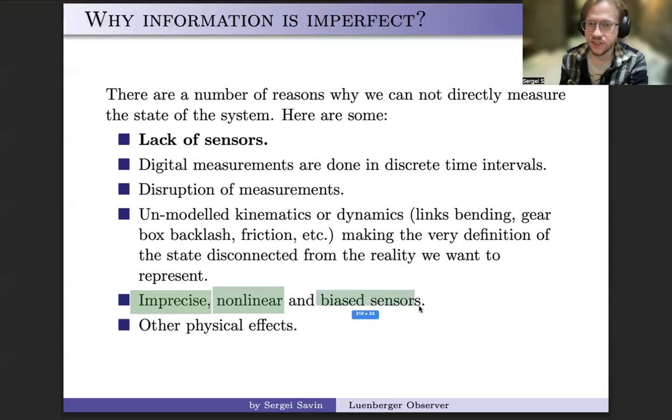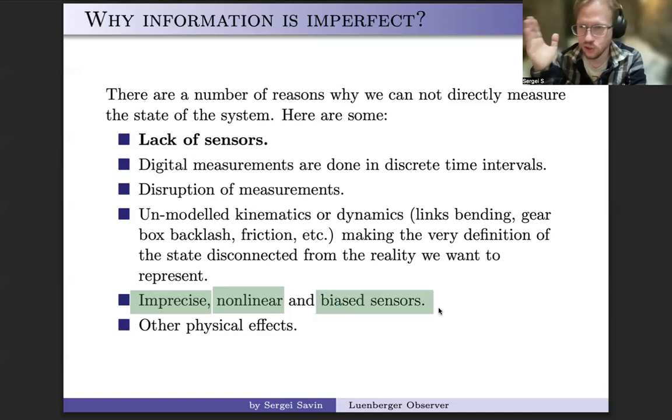Of course, if your sensor is simply biased, as in it always measures 1 degree more than expected, you have to recalibrate, right? Though sometimes, it's not very typical, maybe you would acquire a bias during a long operation, for whatever reason. It could be simply that mechanically the sensor moved slightly because it was installed incorrectly.